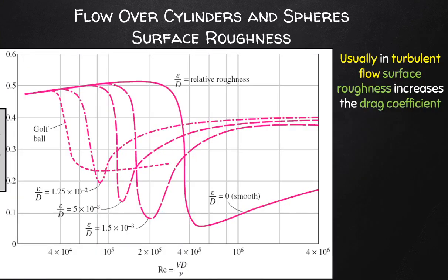Now, since the friction factor is affected by both the surface morphology of the solid interface and the Reynolds number, changes of these two parameters can be used to change how and when vortex shedding will occur, and obviously this will have an impact on heat transfer. But in other cases, if you are interested in aeronautical engineering, it will interfere with how planes fly, how golf balls fly, things like that.